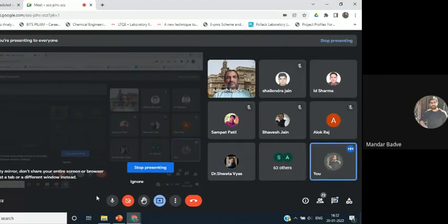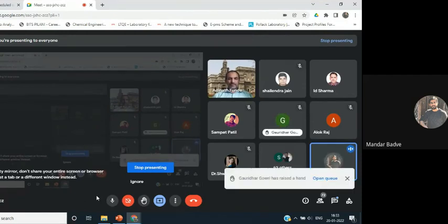I have myself recently joined this Department of Technology, because earlier during my PhD I had a very sophisticated assembly. So here at the Department of Technology, I just did it with a small centrifugal pump and a small plastic tank, and with less than 10,000 rupees, I managed to build a small cavitation setup. But in terms of volume, it is tricky. We still have to use a minimum of 3 to 4 liters, because you don't get those pumps very easily, which generate at least 2 to 3 bar pressures, right? In order to generate 2 to 3 bar pressures, you need at least 3 to 4 liters, because you won't get sufficient head, right?